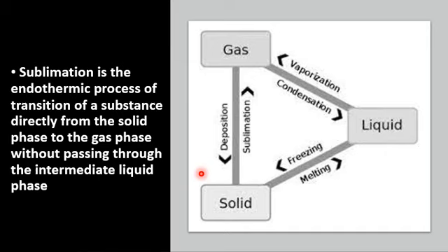So dear student, in the close space sublimation process, initially the solid phase of the material, which is usually in the form of powder, is heated and sublimated, that is, it is converted into a gaseous phase without any liquid phase between the solid and gaseous phase.